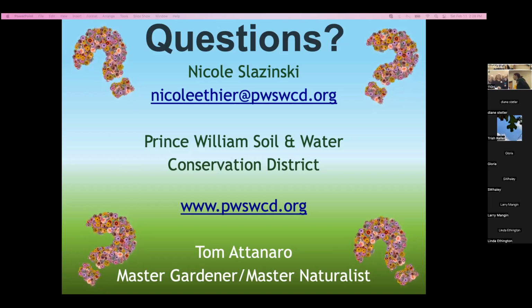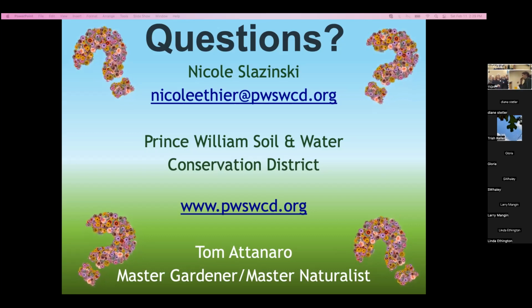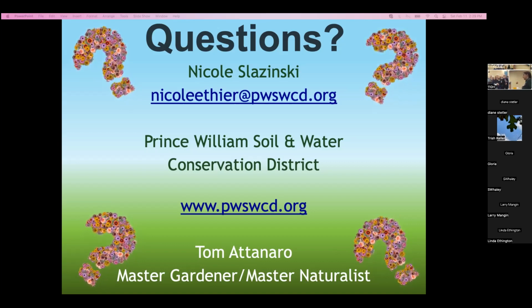What's to stop all the mulch from washing away? Well, the mulch is at the bottom of your rain garden, like in a bowl, so it shouldn't go anywhere. But if you put it on three inches deep and the berm is only this deep and the water rises up, wouldn't it all wash over the edge? It shouldn't. It should be heavy enough to stay in place. If it rains immediately after you put it down, it gets messy, but it kind of locks itself into place after that.